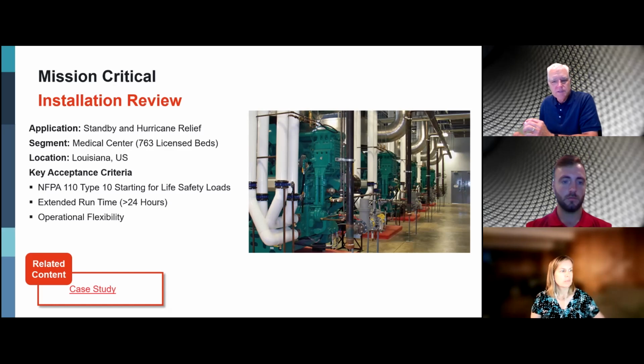Our Lady of the Lake is a major hospital in the region. They have 763 licensed beds, and they were adamant in reducing their risks to subsequent storms in the future. NFPA 110 Type 10 still applies here, as electrical power within life safety must be restored to power side of the ATS within 10 seconds.